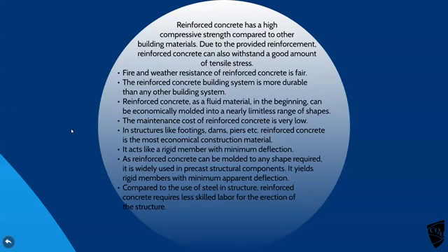High compressive strength because of the concrete, and the reinforcement gives it a good tensile strength. If you didn't have reinforcement in concrete, you couldn't use it for beams or floors. Fire and weather resistant, pretty good. It's more durable than some other building systems. Reinforced concrete is a fluid material when you start off with it, so you can put it into different shapes. Maintenance cost is really low unless it starts to fail or gets damaged.